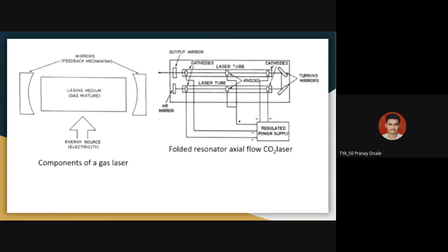With the help of the lens we are focusing on a small portion of the workpiece. By focusing continuously, due to the heat energy in that laser, melting will start in that localized area only, and through that melting and vaporization the material will be removed. That is simple.